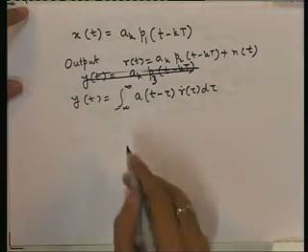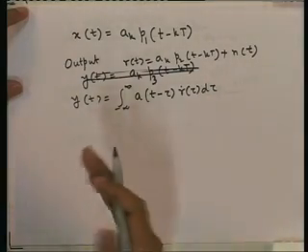This is the output. But we are sampling. For demodulating the 0th symbol, which does not have any shift, we sample at T and demodulate, and then see which symbol was transmitted. But for the kth symbol, we will sample at (k+1)T.